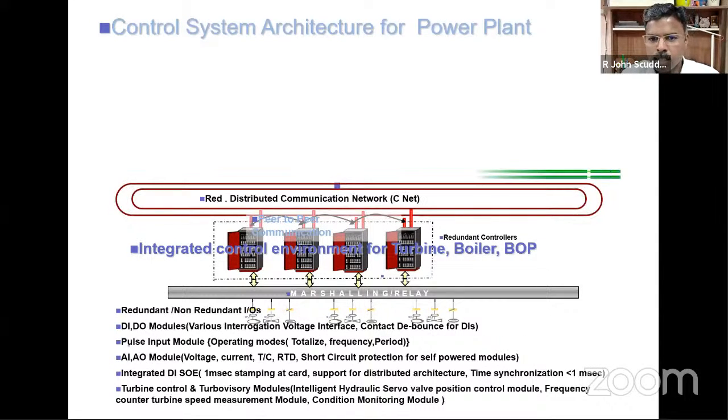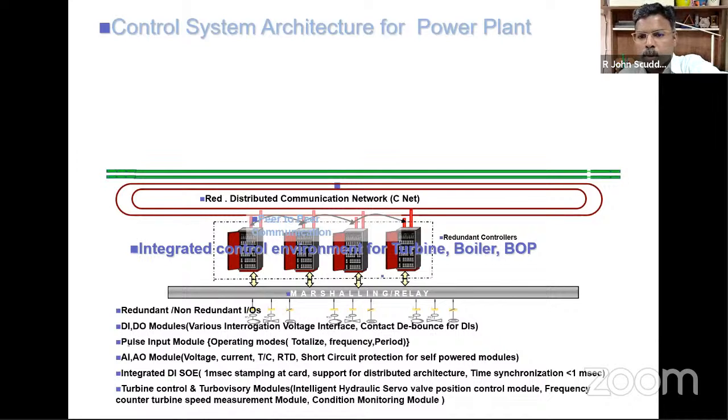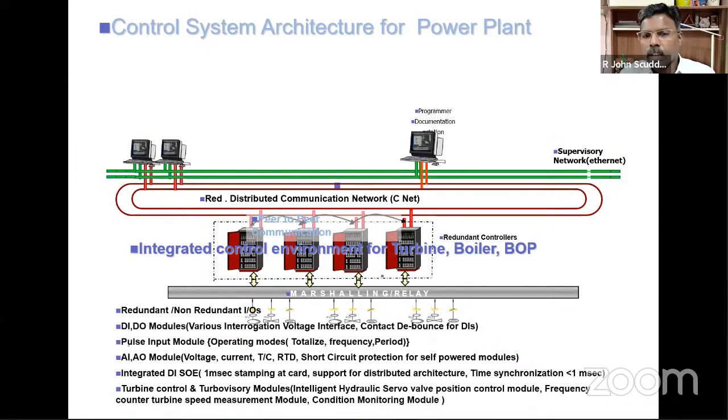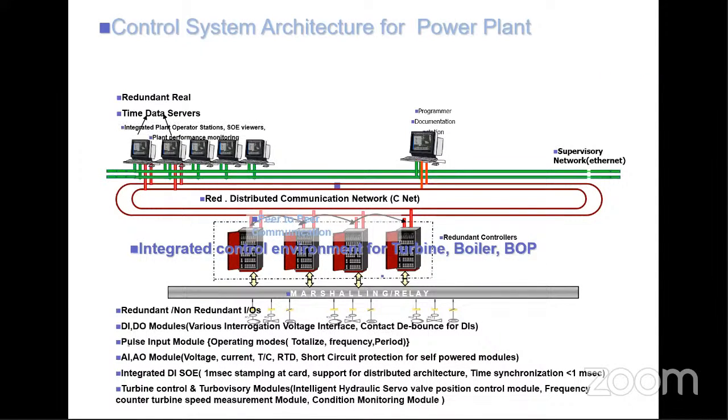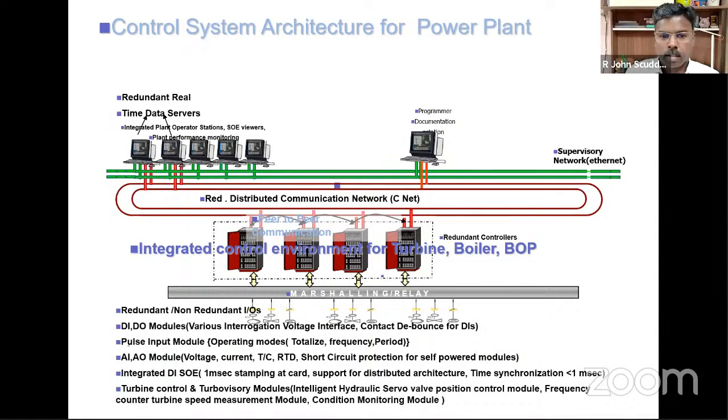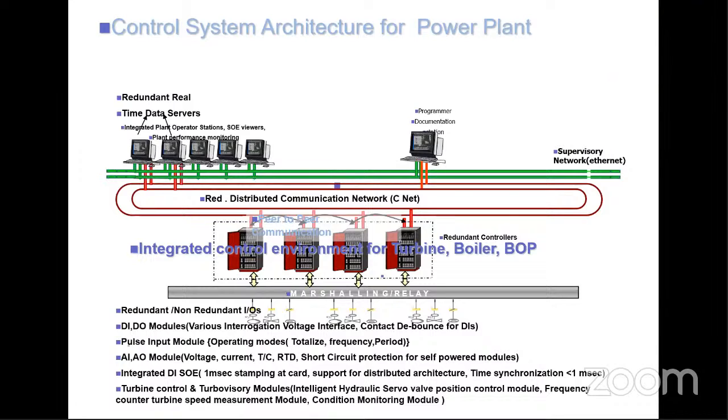As I told you, on top of the control network, both the engineering stations and the HMI servers are seated, so they are able to get all the data. The HMI, human machine interface, is seated in this LAN network. Once it is available in the server, just like Yahoo or Google servers, you are not able to edit any data, but you are able to access or visibly see it. That's how the HMI works, for any data which is already brought into the DCS and is understandable. So the HMI connection is from the engineering station to the server only.